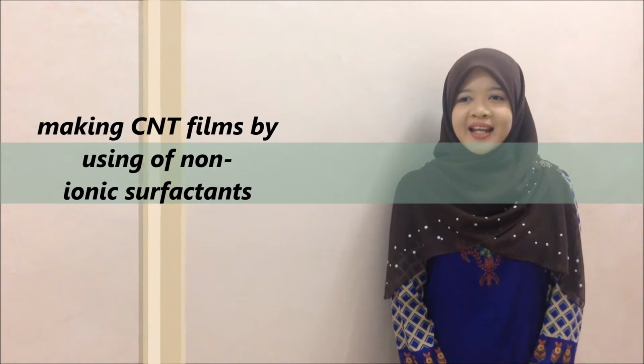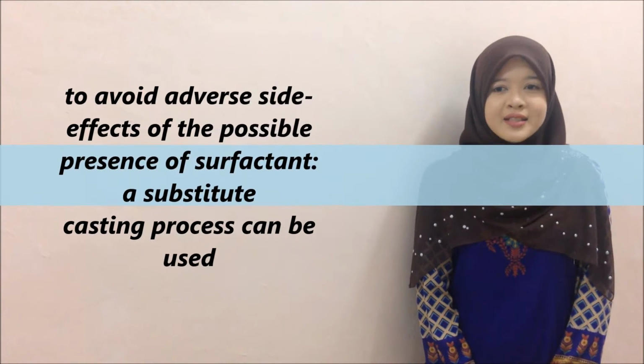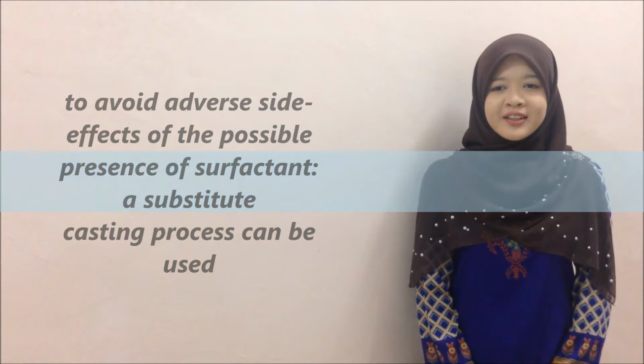The method of making carbon nanotube film includes the use of non-ionic surfactants such as Triton X-100 and sodium lauryl sulfate, which can improve their dispersibility in aqueous solution. This suspension can then be membrane filtered under positive or negative pressure to yield a uniform film. In order to ward off the adverse side effects from the possible presence of surfactant, a substitute casting process can be used, including a flip method that does not need the use of surfactant or surface modification.